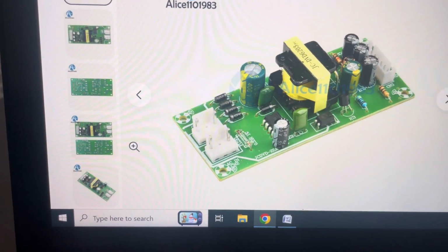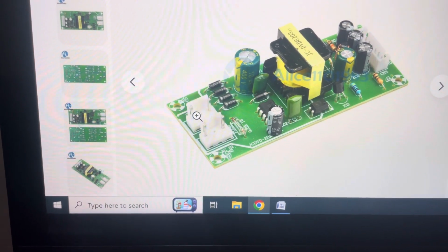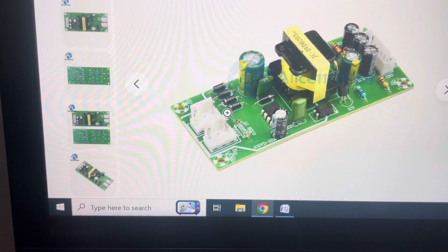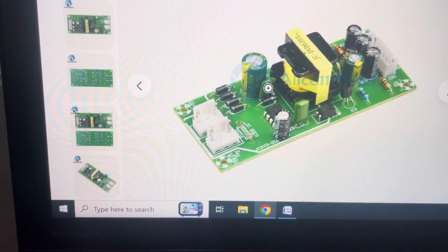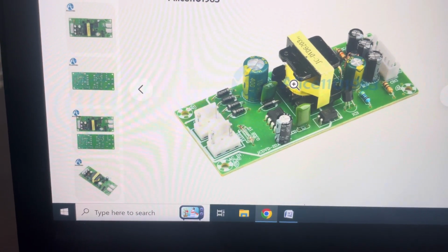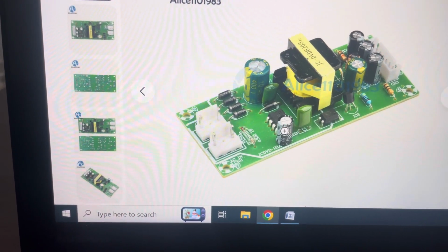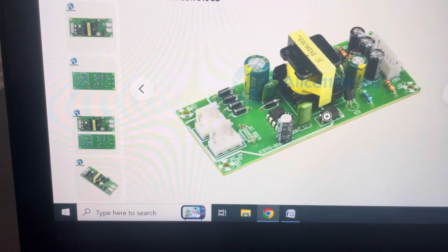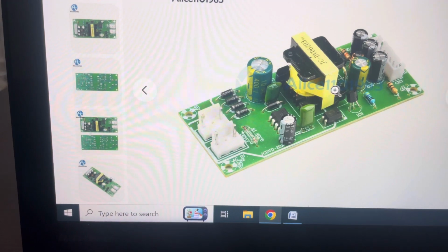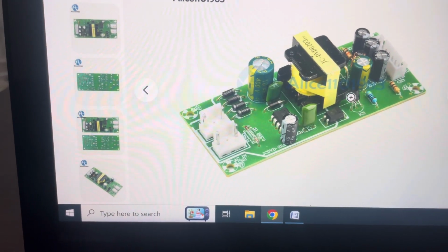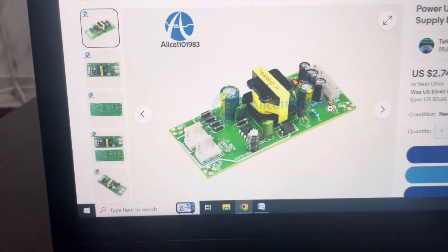In these systems, we give the AC, and the AC is transformed into DC using this capacitor, and that DC is fed to the chopper. Wherever you see a chopper, you will see a chopper driving IC and an optocoupler there. So here it will be driven, and the chopper will give output, and we can receive the particular driving voltages.